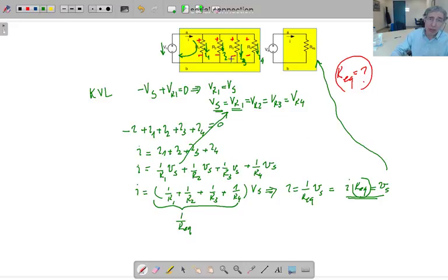On the other hand, the left hand side circuit current is this. So that is that current. And this current here, make it red, is this current. So they are the same. So that means this is the equivalency definition. Those two currents are equal. So if you took these four resistors off and put that equivalent resistance in, this current does not change.